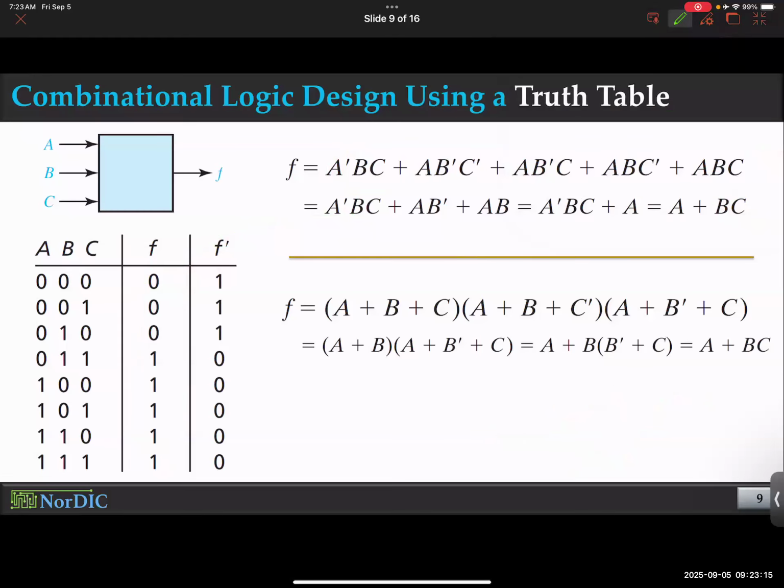All right, now let's take a look at a different approach to getting this functional Boolean output, which honestly, I think, is going to lead to an even more complicated expression, but there are reasons why people still talk about it, and we will talk about it here. So what you saw first was a sum of product expression. Here is why it was named so. You eventually take a sum of products. So SOP, sum of product.